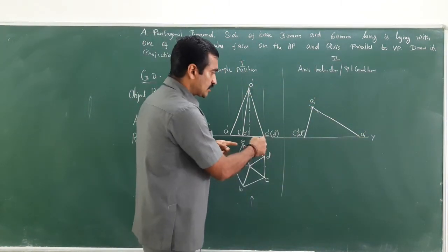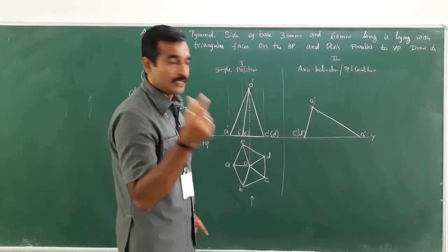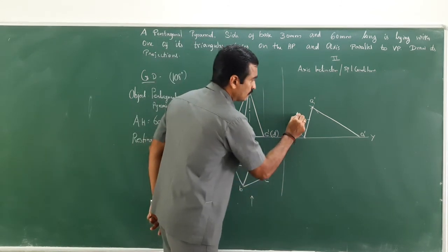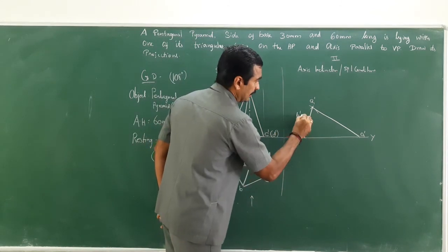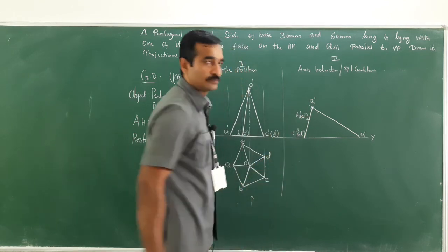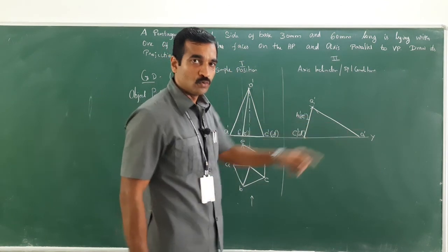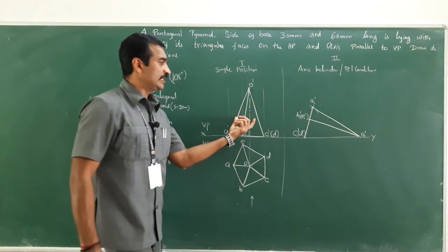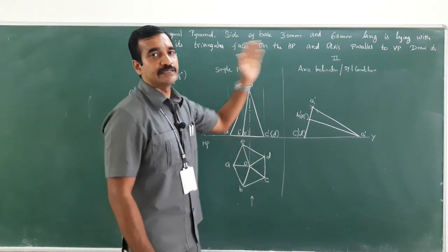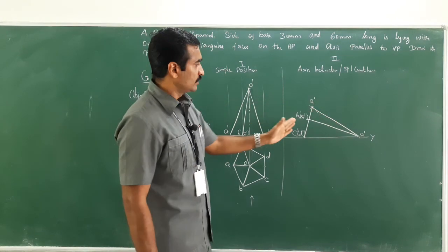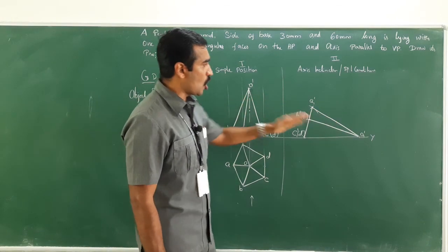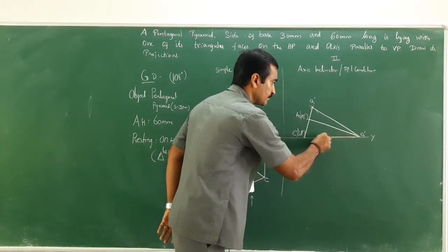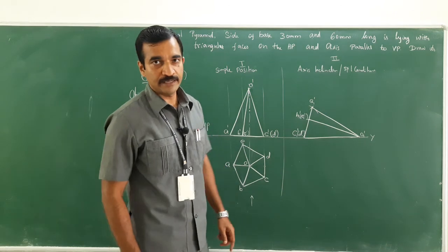Now measure the distance between C and B in your compass. Keeping at C, cut an arc. And this point becomes B1 dash and E1 dash. Now connect BO. Look at here. This particular object has been transformed. That means keeping CO on the XY line. Clear? Right.